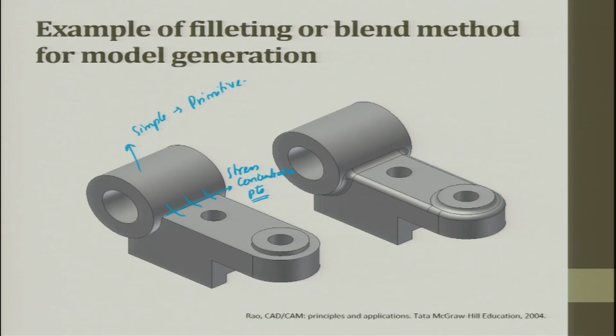If this is a flat one which just butts against a surface, then this will lead to a failure very fast. So, here what we do is we have the option of filleting. Wherever there is a sharp edge, there is an option of filleting. Filleting will enhance the safety as well as the life of the component. So, these are some examples wherein filleting or blending methods for model generation is possible.